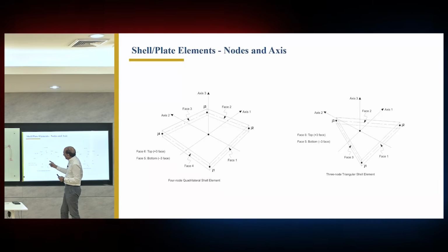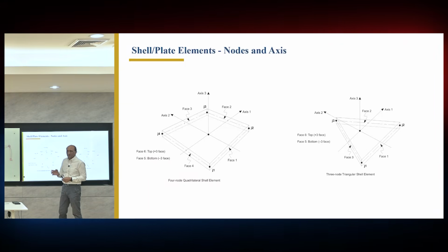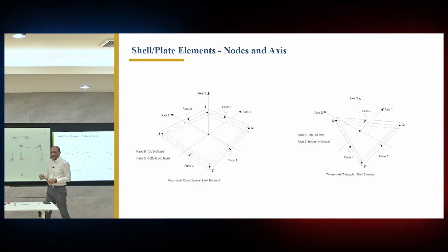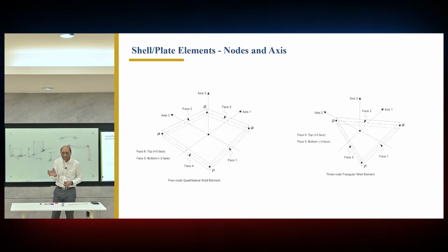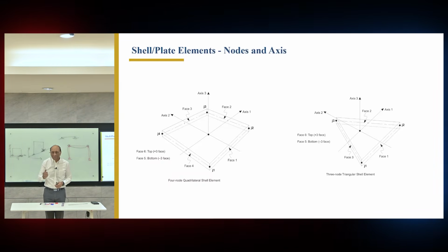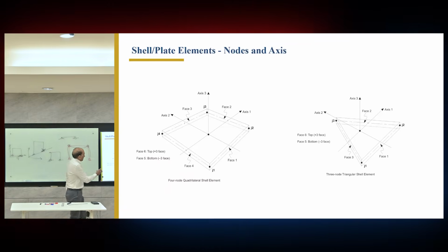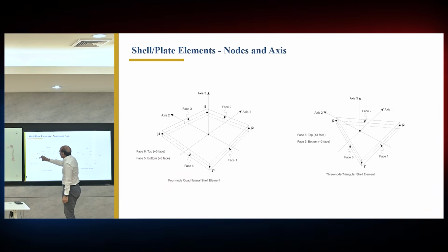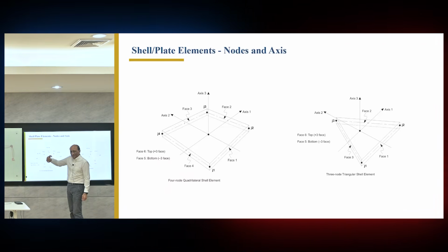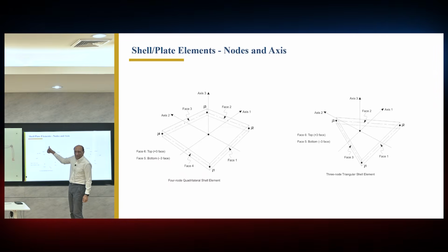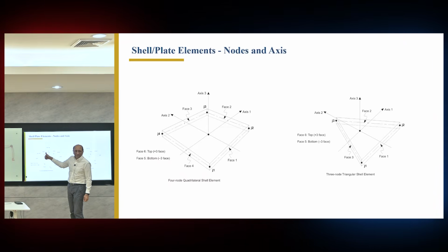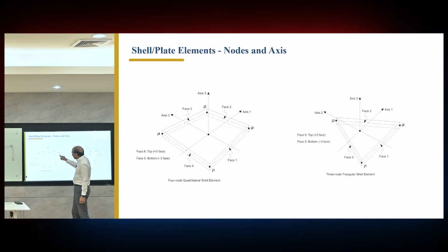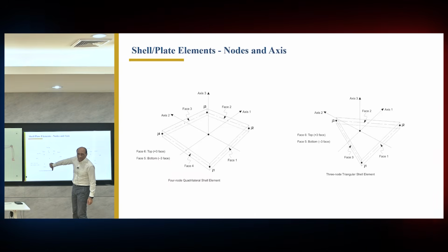Numbering is easy to generate: just keep adding 2 and then you're generating. So it was easier, and people started to do it like that. But in finite element, we must have a direction of the numbering, because that will decide the orientation of the element. If you number it like this, 1, 2, 3, 4, that means you are going like this, and this one is your z-axis, the 3 positive axis. If you number 1, 2, 3, 4 the other way, then your z is downward.